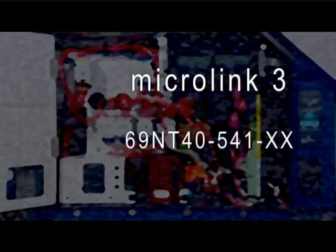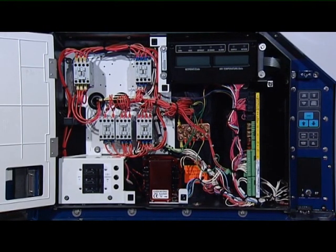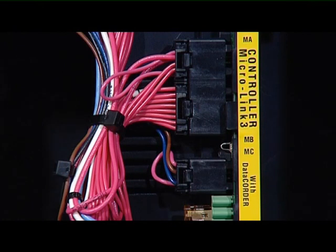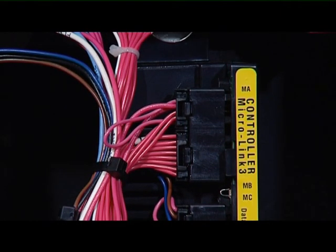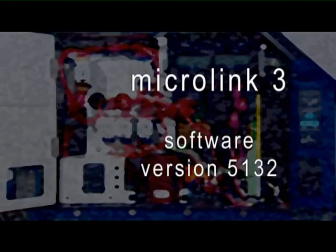Microlink 3 units are the 69N240-541 model. These models also have only one component, which includes the controller and the data recorder. The Microlink 3 controller is compatible with the Microlink 2i with the same operational software number 5132, but it cannot be mounted onto the Microlink 2 units. However, the Microlink 2i controller cannot be mounted onto the Microlink 3 units either. The software program version for the Microlink 3 is number 5132.